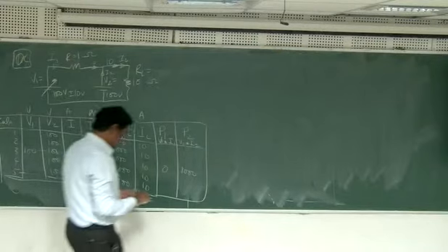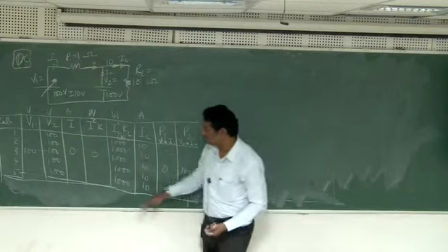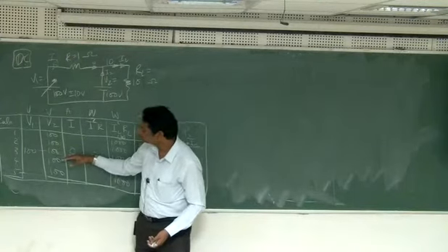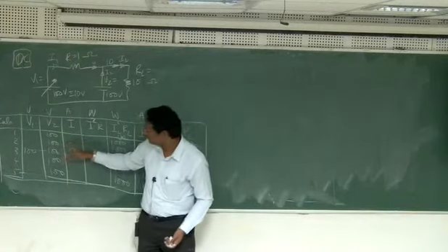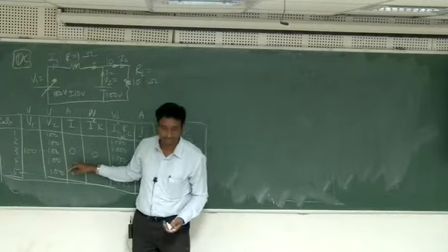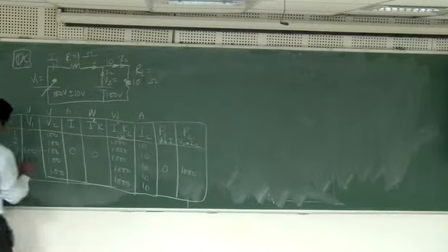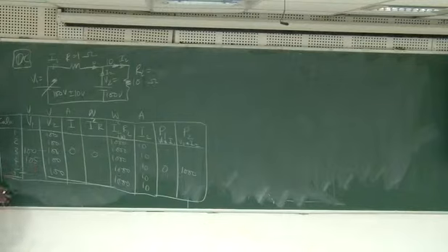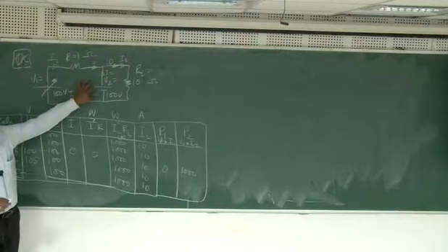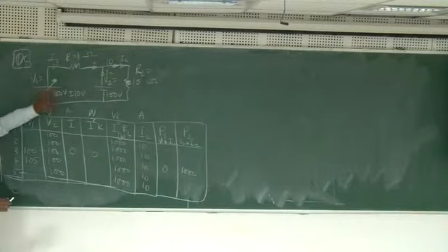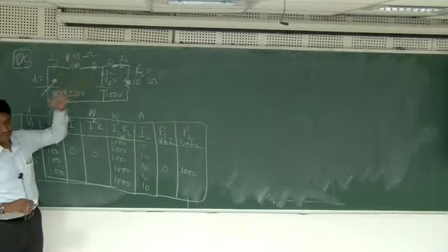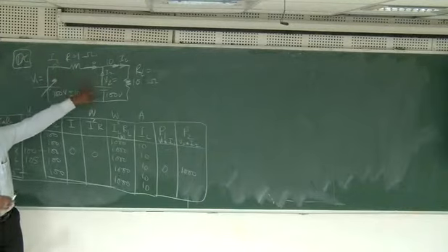So I hope you are following what is going on here. Slightly, let's increase V1. I want to use 105 volts at V1. I increase the supply voltage here. Then immediately how much current will flow? 5 amperes definitely has to flow, because this minus this is 5 volts divided by 1 ohm.